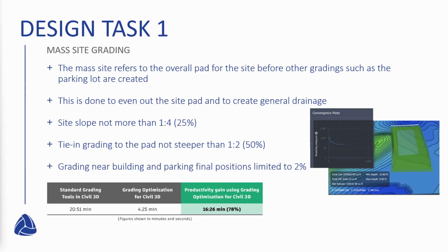Just to quickly go back to that convergence plotting that I was talking about earlier, you will see it over here. As you enter your parameters for your site, you just have a polyline drawn out. You enter your minimum and maximum slopes and then just run it. As you can see on this log chart, the convergence plot runs from a high convergence, and the more iterations it moves through, you'll see it physically changing your contours, updating the slopes, updating the elevations in this interactive viewer.